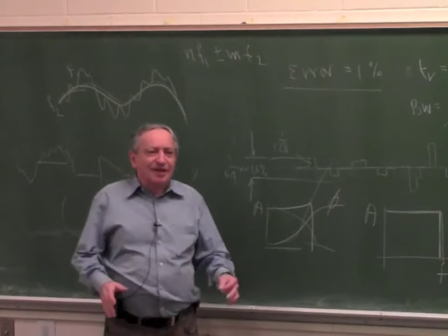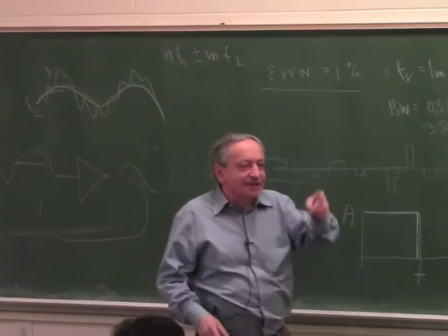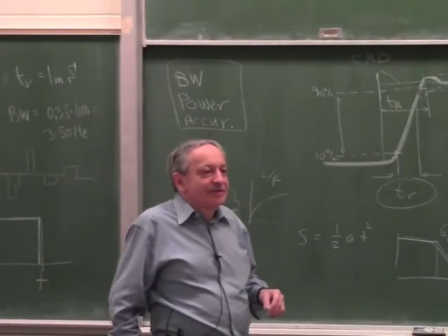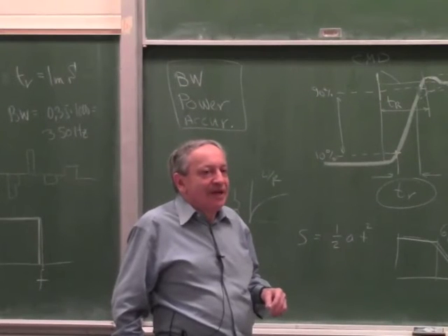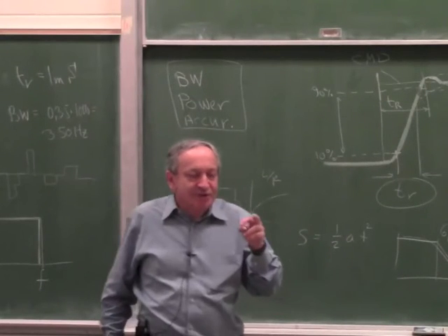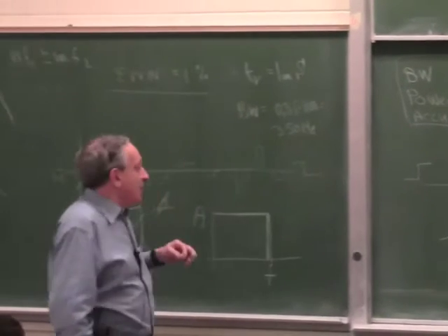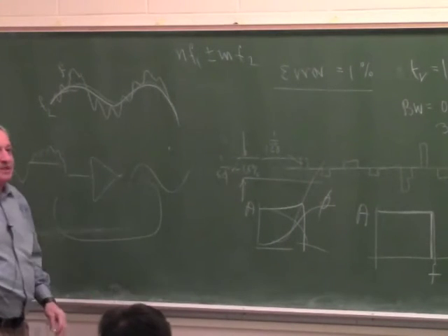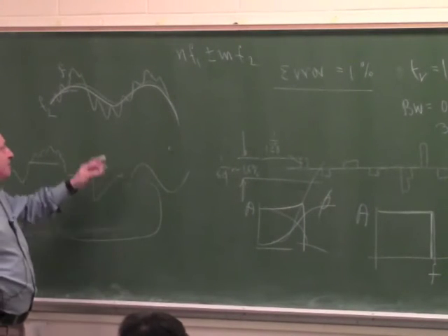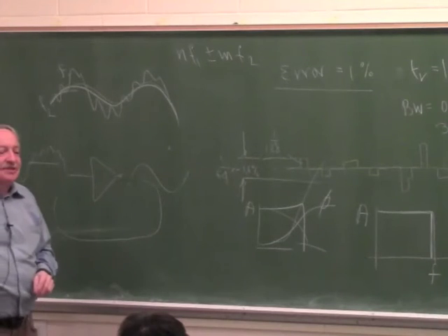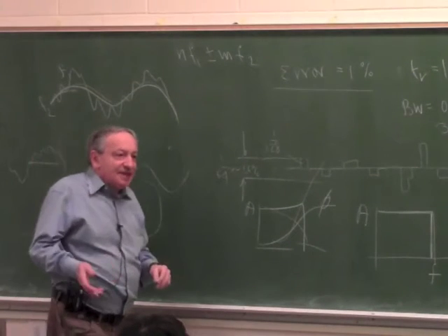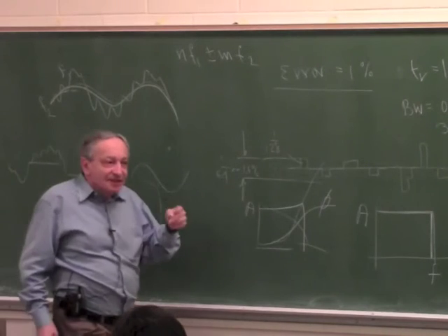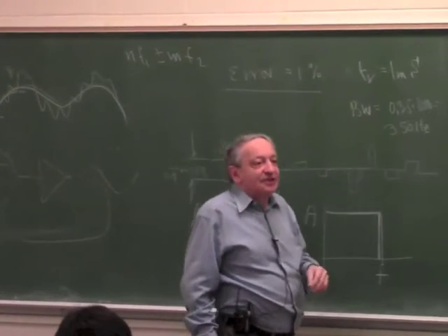A third reason is practical, it has nothing to do with theory. Yes? If you limit the bandwidth, can you get better gain at the regions you want? Yes, but I'm saying something different here. Even if the amplifier overall has limited bandwidth, I don't want to feed into it a high frequency. One reason is aliasing if it's a digital front end, one is intermodulation, but there is another reason why I don't want to feed into it a high frequency.